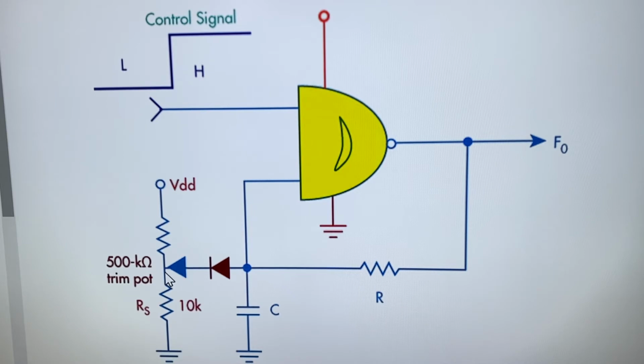So that will be by adjusting the voltage here to a voltage less than 2.7, as long as this diode is conducting. So the capacitor will stay there. But when you apply the control signal high, when you have a 1 here and a 1 here, the output will be 0. So the capacitor will start discharging from VT positive to VT negative. So you have to hold here the voltage a little bit less than VT positive. I said before VT negative, no, it's VT positive, okay?